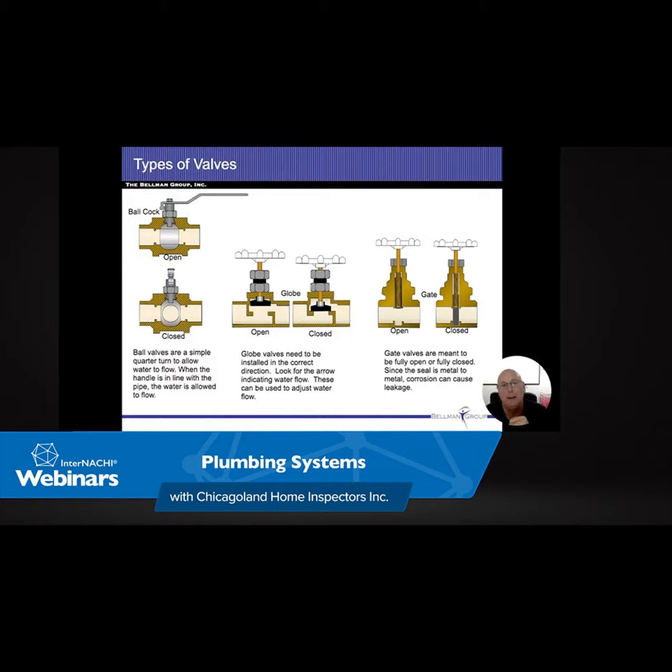All right, pump components. I think we kind of chatted on this already. We're going to have our pump, our pressure gauge, our tank as well, the on-off switch that comes there, an isolation valve, and usually some sort of pressure relief valve. Not too often do we see that. Pretty much the only pressure relief valve we're going to find is on the water heater itself. The only time we see pressure relief valves is when there's either a backflow prevention device or some sort of pressure reducing device, and then we'll see it built into that.